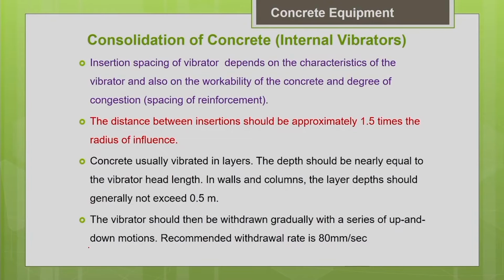According to the consistency, you need to vary the amplitude and the frequency, but that is mostly possible only in factories. Very commonly at your job site, you can see that they change the spacing of the vibrator just by looking at the consistency of the mix.